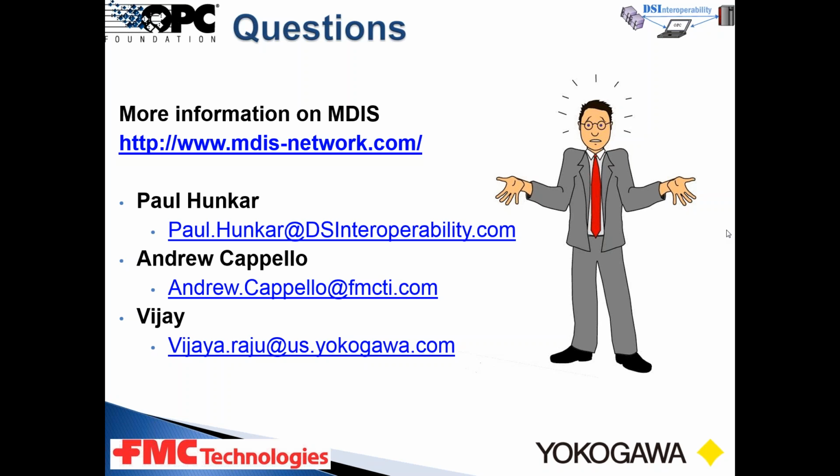Thank you, Andrew. A little addition from my experiences with Modbus is that Modbus doesn't have security. It doesn't have some of the robust communication capabilities that OPC UA would provide too. So the error handling and the security aspects of UA add a great additional feature that you won't get out of Modbus. So there's quite a bit of difference between the two. Let's see what else I have for a question here.